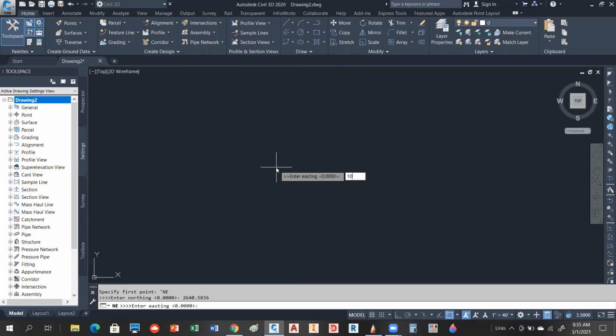And then it should be prompting you for the easting, 1041.5794. Now, you may not see anything because your line's probably way up there, so don't worry about that. It should be prompting you for the next northing. So I'm going to go ahead and type in 3183.3395 and 1070.0916. Okay, there's my line.